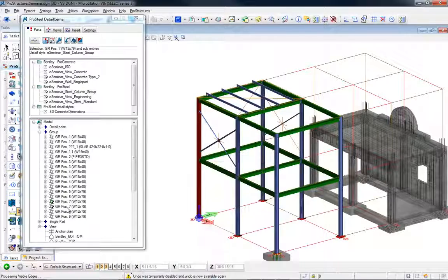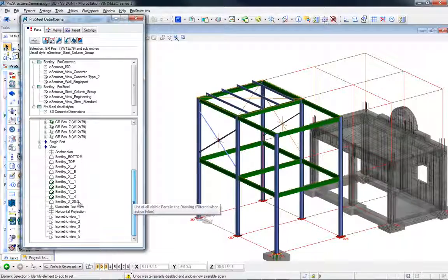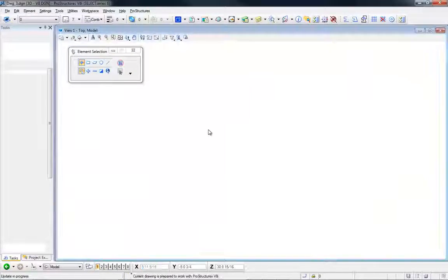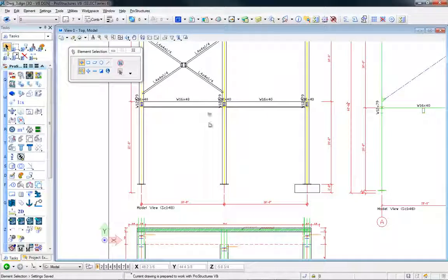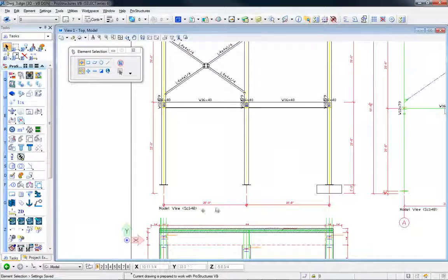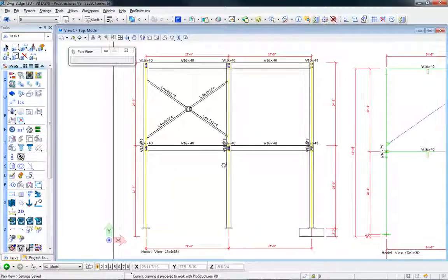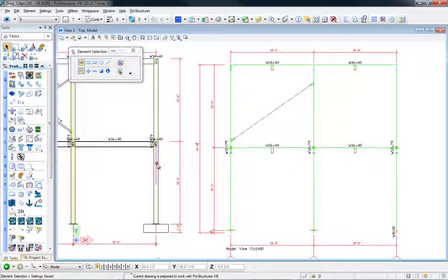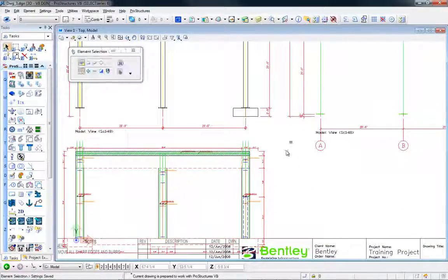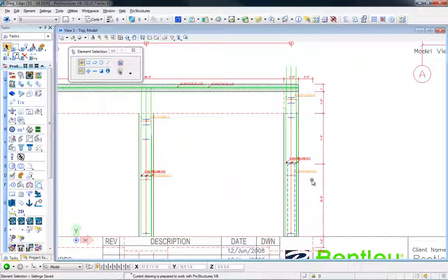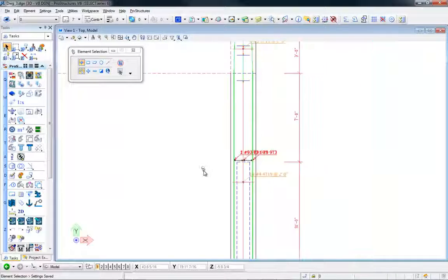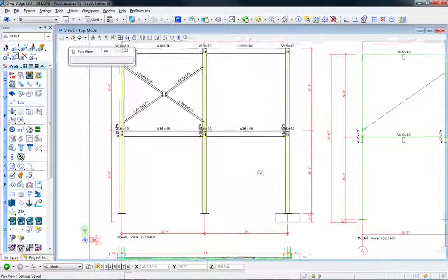Okay, let's have a look. Closing here. You see they have turned green. The 2D drawing has been created, and I open that. So this would be my first view. I have my dimensions, I have my annotations, and this would be the second view. You see it's the same drawing, but just by assigning a different style, the 2D result is looking different. And here for my concrete, I can go in here now and I can move the flags around, finishing it up a little bit.